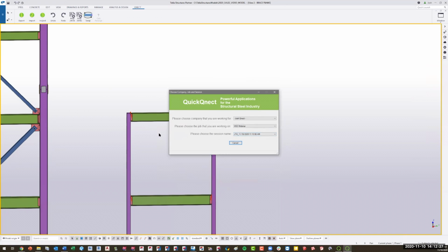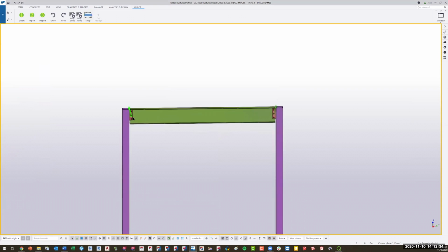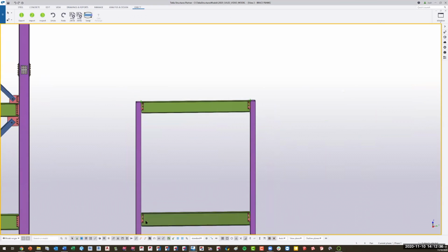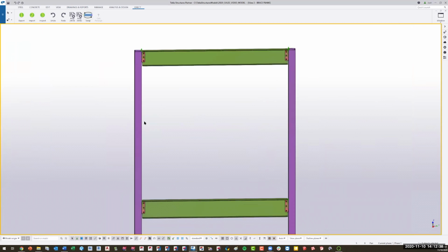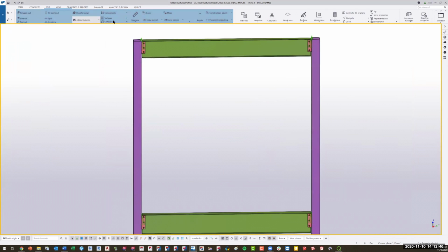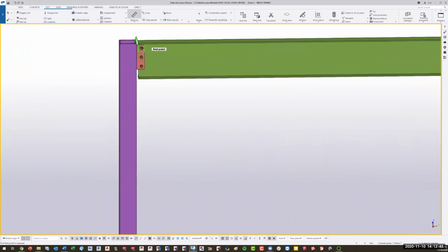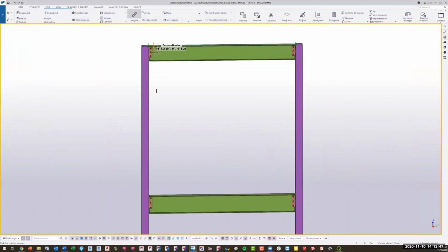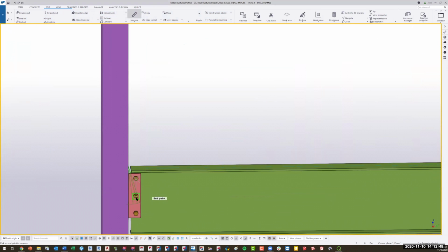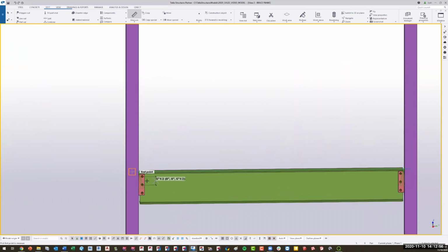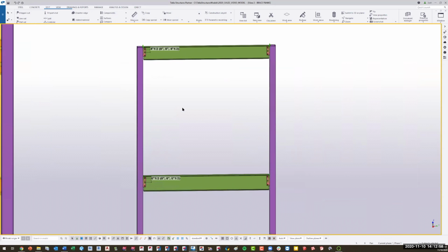So you had 5 bolts on top, 6 bolts on bottom here. And now we have 3 on top, as well as 3 on the bottom. So let's look at the vertical spacing of these. We had 3-inch vertical spacing. Now we have 4.5 here. And we have 5.5 here. Now this can be controlled in quarter, half, or 1-inch increments. We can definitely define or control how we want to do that.